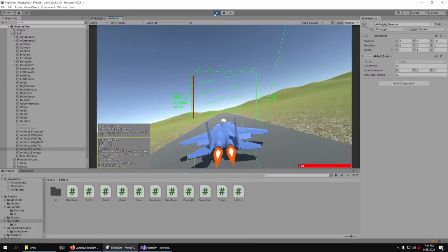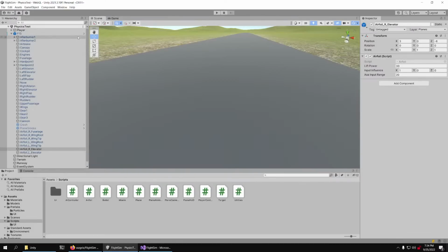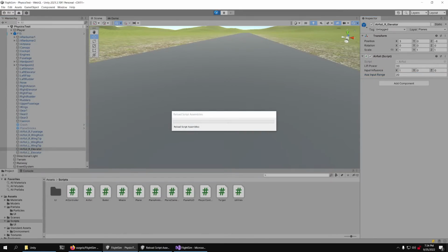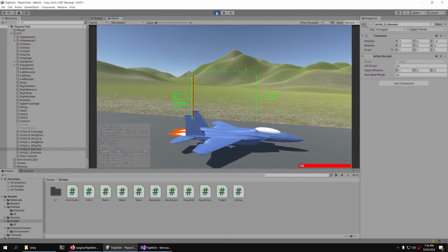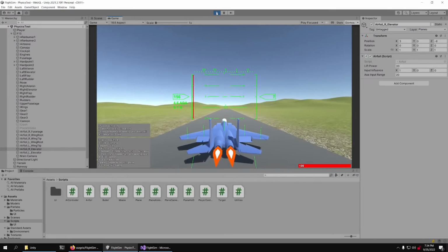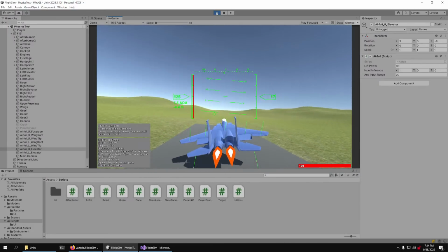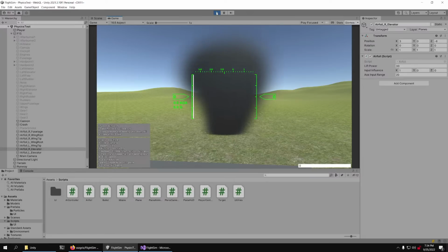And it's also causing the airplane to pitch, but it's very hard to control that. Okay, I think I should make the ailerons a little bit weaker here. So just changing how much lift they change at the maximum input from 20 to 5, that should make it weaker. Okay, so I was just flying there, but it was incredibly unstable.